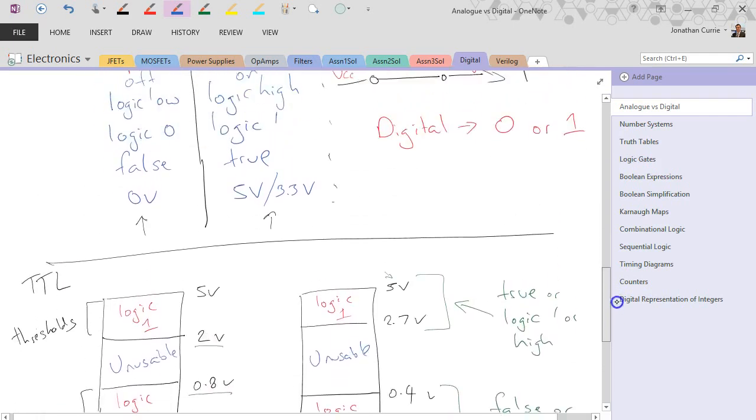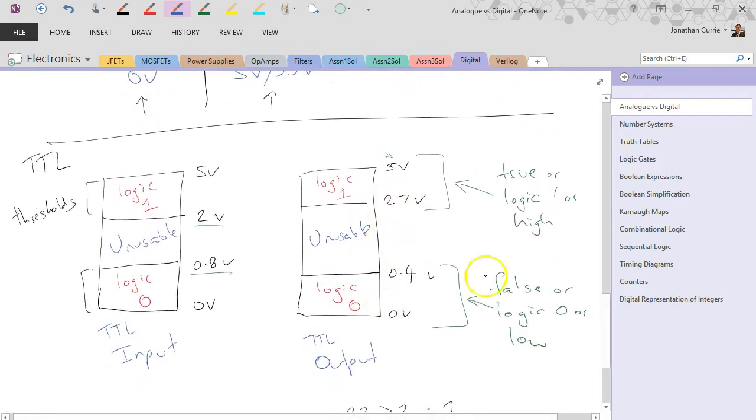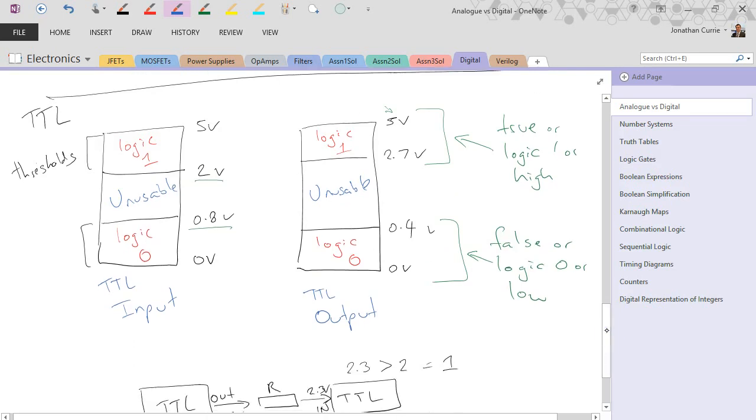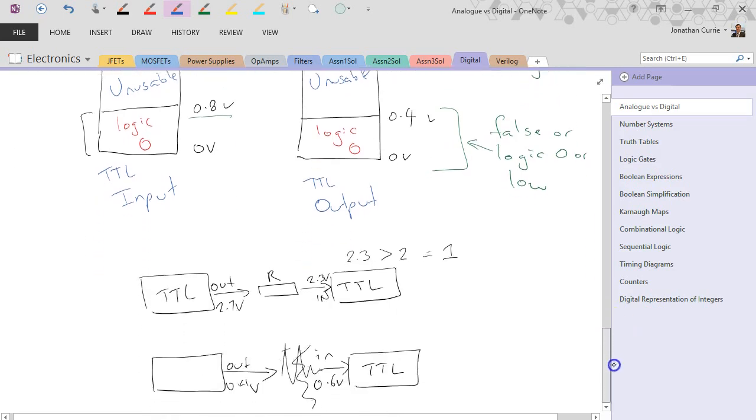And noting that there is a tolerance around that. So a logic 1 would fit into, let's say, the output of 3.3 volts. Okay, or a logic 1 would also fall into the input of 2.5 volts, if we're looking at it from an in point of view. So different ways you can look at the same signal, just giving a little bit of operational tolerance.